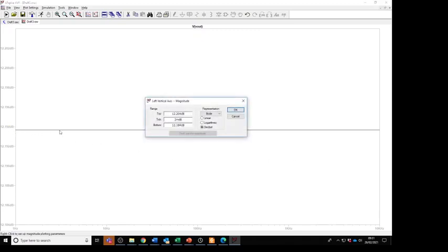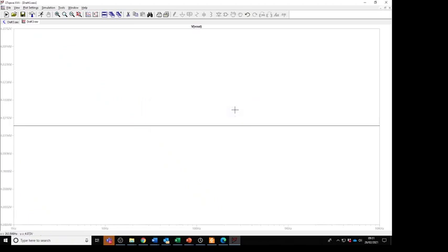If we don't like dBs, we can plot it linearly. And look, our gain is 4, and this scale is very tight, so we've got a very good 4.07 whatever gain across the whole frequency range for this amplifier. So that's pretty good, isn't it? We get a good analysis of what's going on.